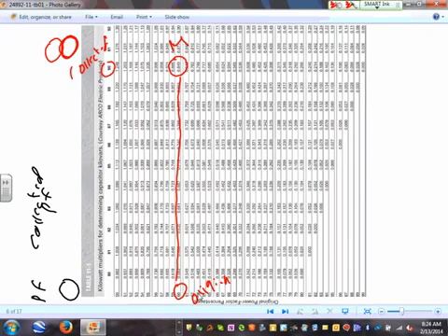Everybody knows how to read this table. Can I have thumbs up, because it's so important how to read this table? Here's the original power factor. We'll be using it in a second, guys. Here's the corrected power factor. Here's the multiplier that you need to correct. Everybody knows how to read it? Yes? Adam? Good? Okay. So that's the corrected power factor. That's how you read this table.